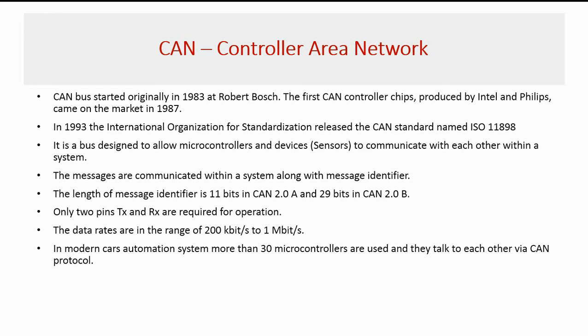Instead of any address, an arbitration ID is used. All the nodes on the CAN network can receive the frame, and depending on the arbitration ID of the transmitted frame, each CAN node on the network decides whether to accept the frame or not.